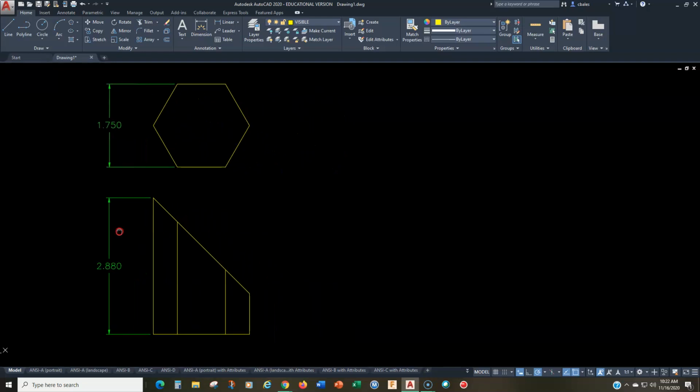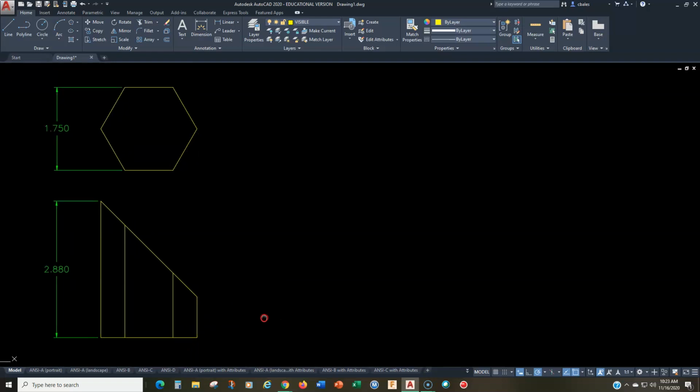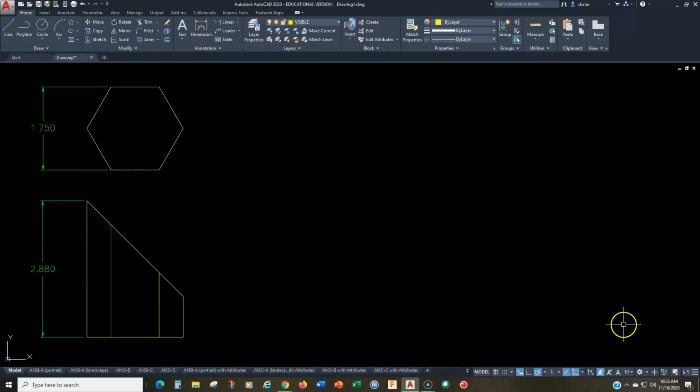All right, so now our task is we're going to unroll this hexagon, right? Remember, this is like a hexagon box, a box that's empty in the middle. So now we're going to unroll it. What we need to do when we unroll it is unroll the sides, and we're going to do it right here in this space, right? Because that's the most logical place because we can project it straight across. We need to unroll the sides, and then we also need to take care of the top because there's a top to this and a bottom, right? So we're going to do both of those, all right? So let's start with the unrolling here, okay?